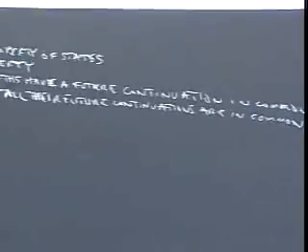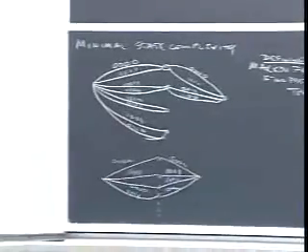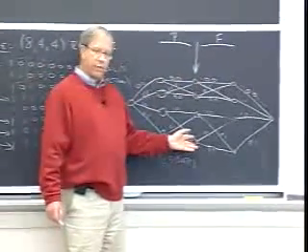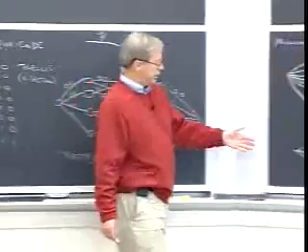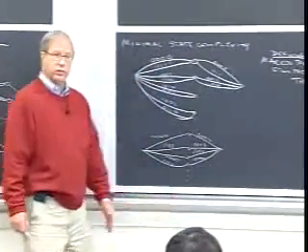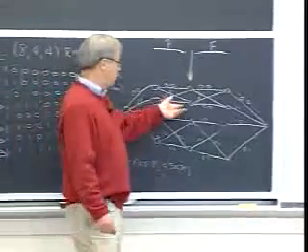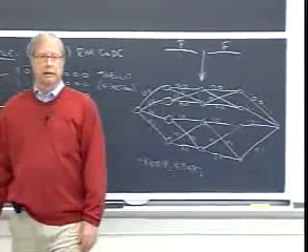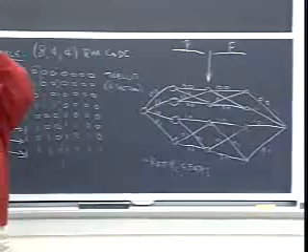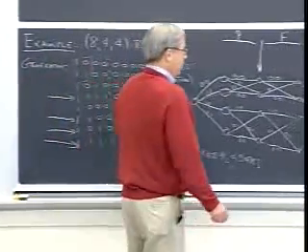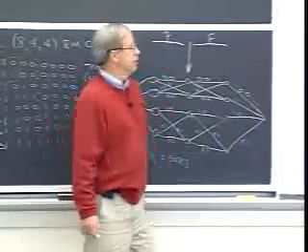Okay, so you can see it very concretely from the trellis diagram. This is the property that we need. You can see that for this particular code, we do have the possibility of combining all 16 possible states here into 4, because we can combine them all pairwise in this way. This is going to come from the linear property of the code. That's why everything is so symmetric. But we can't go any further than that.